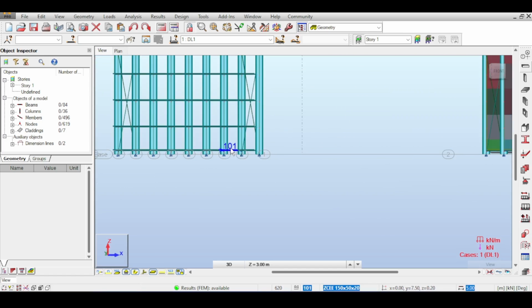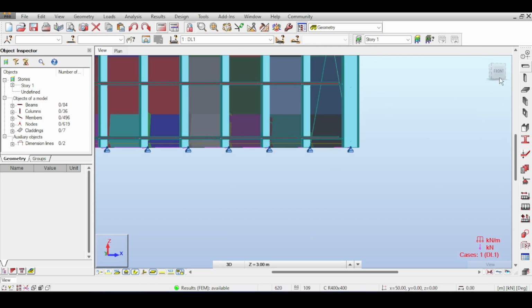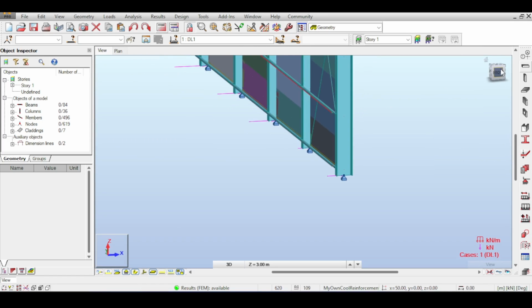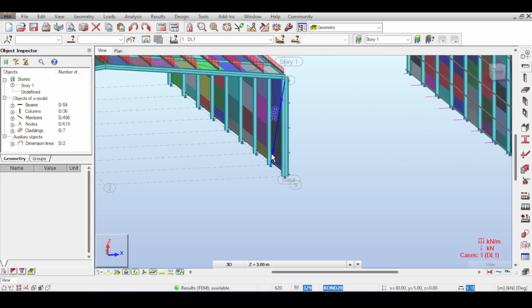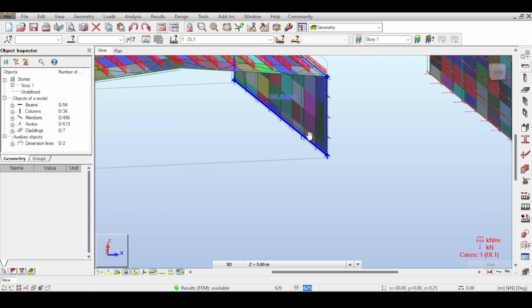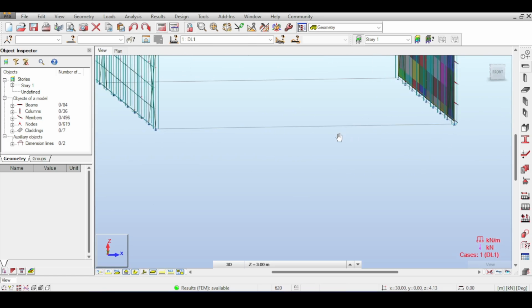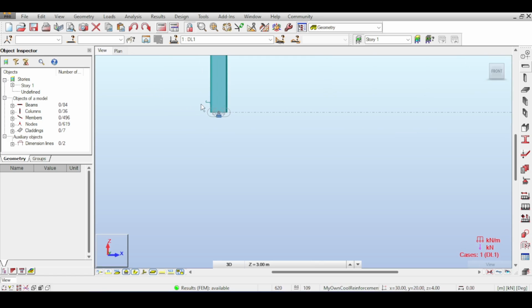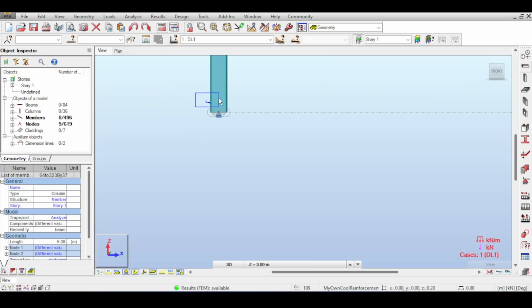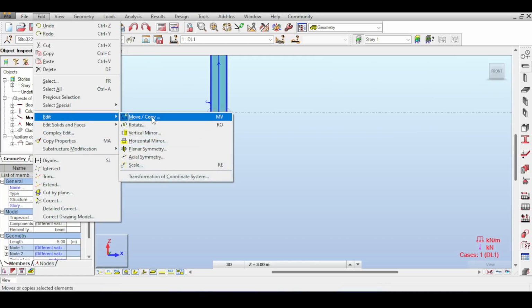And here, let me take a look here. Here I have the loads, right? Because I saw them. But here I don't have the loads. So I think yes, I think okay. Okay, I think that, no, I'm really surprised, I'm genuinely surprised. But I think that Autodesk Robot, when you have a support and you have a cladding, it just distributes part of the loads of the cladding to the supports, which is news to me. I have never expected that, but well, it happened, so now we know how to do this.